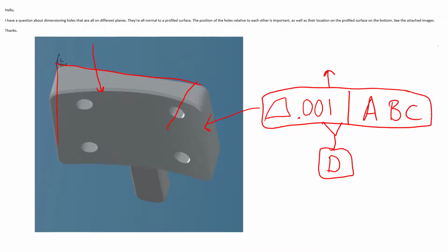Well, as soon as we do that, if it is not a plane, a datum defaults, if it's a curve or a cylinder or things like that, if you're using a surface, a datum automatically defaults to the axis of that. So what we're calling out when we call out this datum D is, if this was a perfect curve and it made a full cylinder with that curve there, that would have some sort of axis. That axis way out in space, and remember, it depends on how truly big this radius is, that is what datum D is.